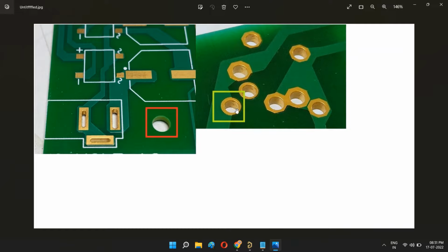application, and this is for conductive application, that is, this will be used for active devices. This kind of through hole pins we will use in through hole lead capacitors, resistors and diodes, etc. And these types of non-plated through holes we will use mainly for mechanical support. So that is an idea about these two main types of through hole pins.